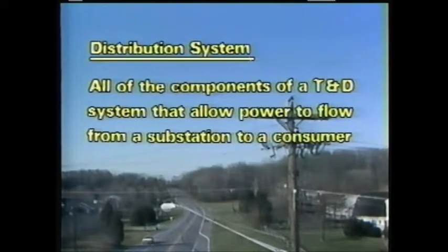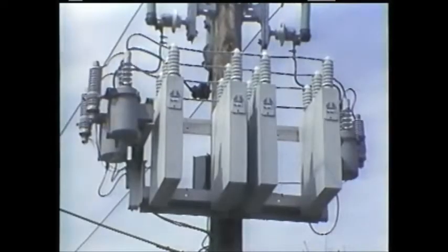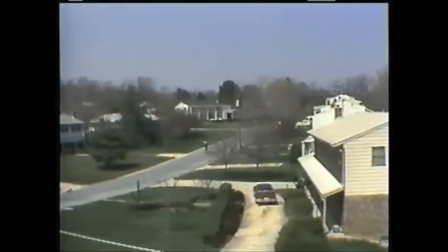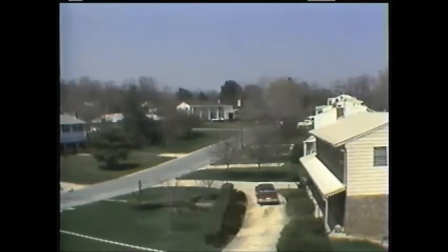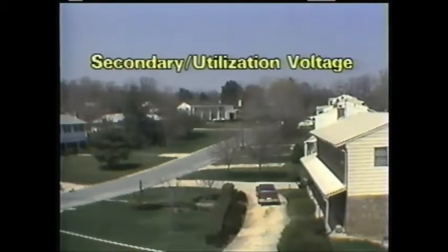Right now, let's review some of the things we've covered so far. First of all, we defined a distribution system as all of the components in a T&D system that allow power to flow from a substation to a consumer. Some of the components that we've seen are transformers, voltage regulators, capacitors, and various protective devices. We've also told you that in a typical distribution system, electricity is supplied at different voltages. Typically, these voltages are classified as primary, or distribution voltage, and secondary, or utilization voltage.